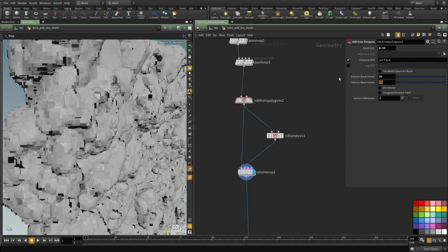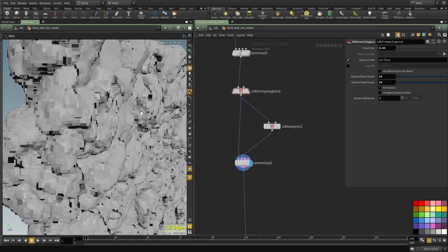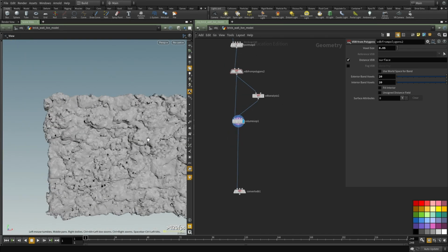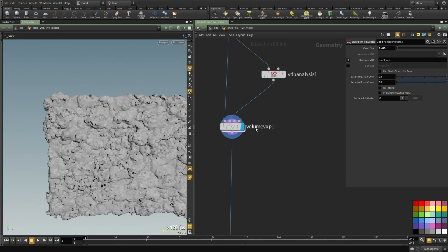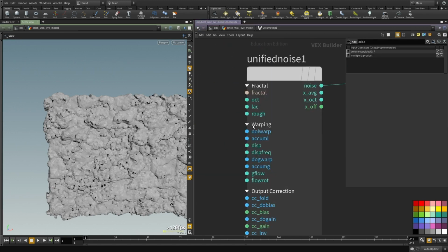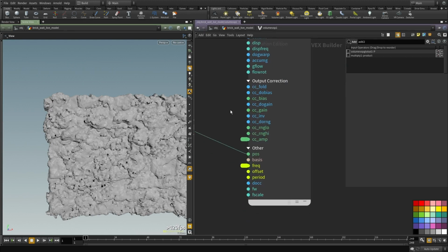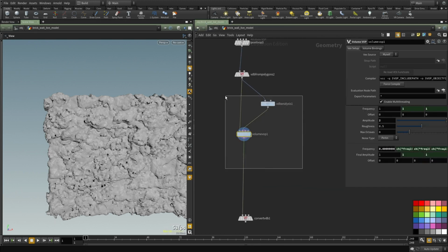And let's increase this to 2020. I'm always careful with this because the bigger the expansion, the slower it's going to be. Okay, cool. So let's leave it at that, and let's expose one more thing which I need, which is the offset. Let's find where that is. This guy. So I want to offset the noise because I'm gonna copy this modifier and redo the same thing again. So I'm gonna copy this.